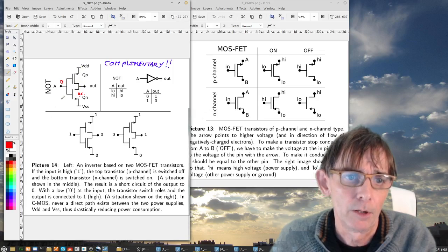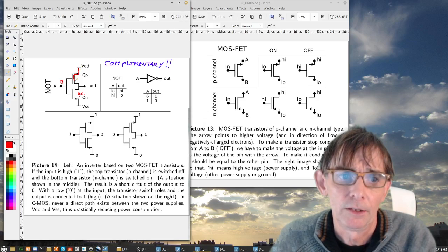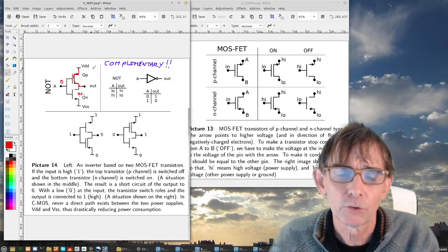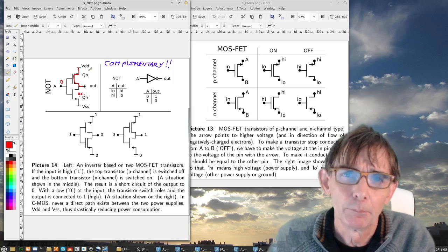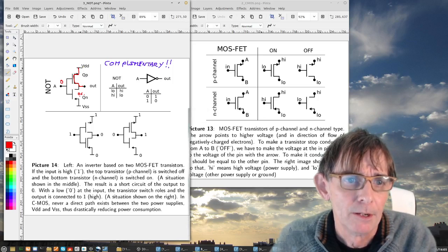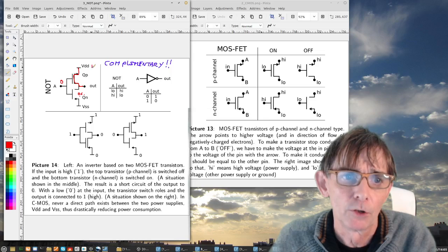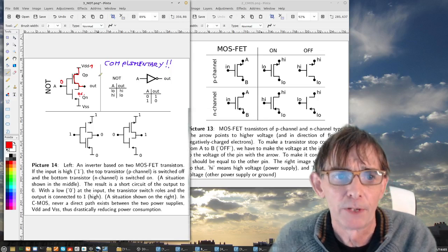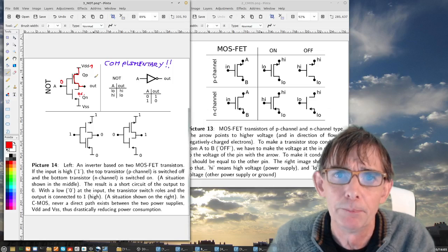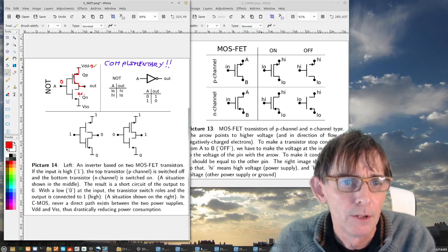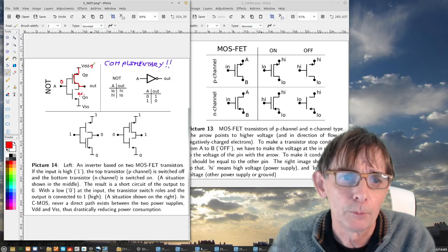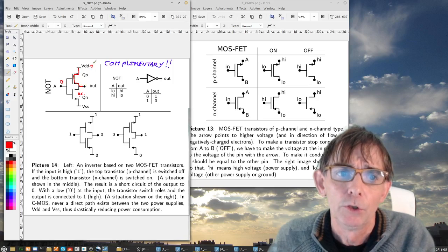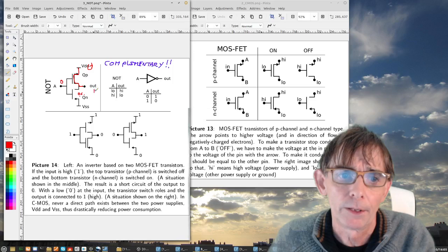So we now have a path from the drain voltage here. It's called VDD. It's a little bit inconsistent sometimes, but never mind. So we have a path here from what is a logic 1, that is the supply voltage 5 volts or whatever voltage you use, maybe 3.5 in modern computers. But never mind, the output now is directly shorted to the logic 1 and you get 1 at the output.